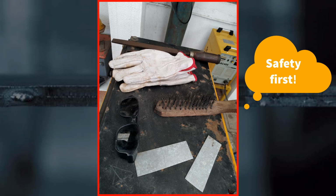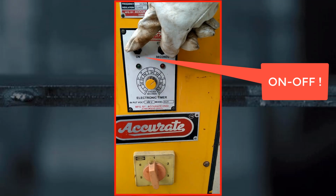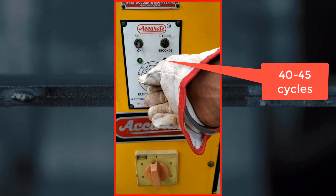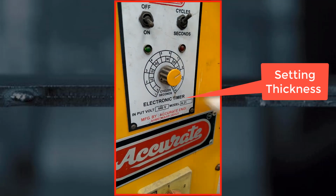So here we are using hand gloves, goggles and a wire brush, and two galvanized iron sheets are placed. It means these are the two galvanized iron sheets that we are going to join. First of all we have to switch on our setup by the on-off switch, and then we can set our cycles, also in terms of seconds.